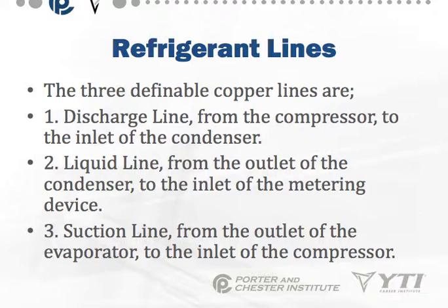Suction line from the outlet of the evaporator to the inlet of the compressor. This is always gas. You should always have vapor refrigerant in this, and it's going to feel cold to the touch.